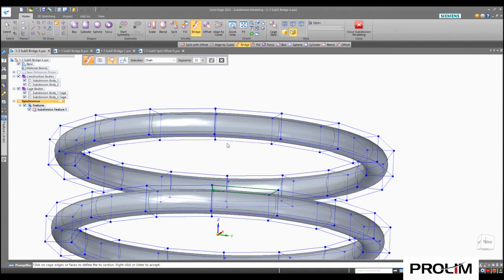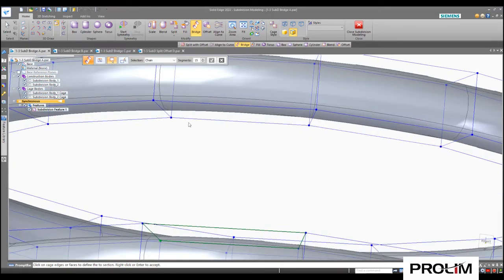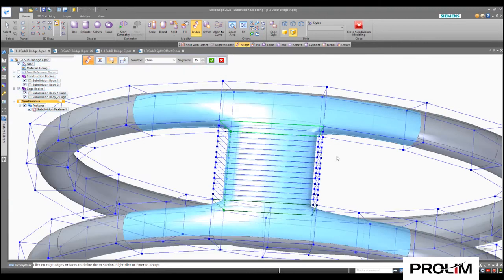And now you can see before I click anything, I'm getting a quick preview of that vertices line. So you can see that it's connecting from this point to this point, and that's going to control if I want to twist in this part or not. If I wanted to twist in it, maybe I would go over here to this portion to put a twist in that. We'll look at that a little bit later, but always be mindful of where that vertices is heading. And Solid Edge does a really good job at giving me a quick preview before I maybe click the wrong thing here. I'm going to go ahead and select that,